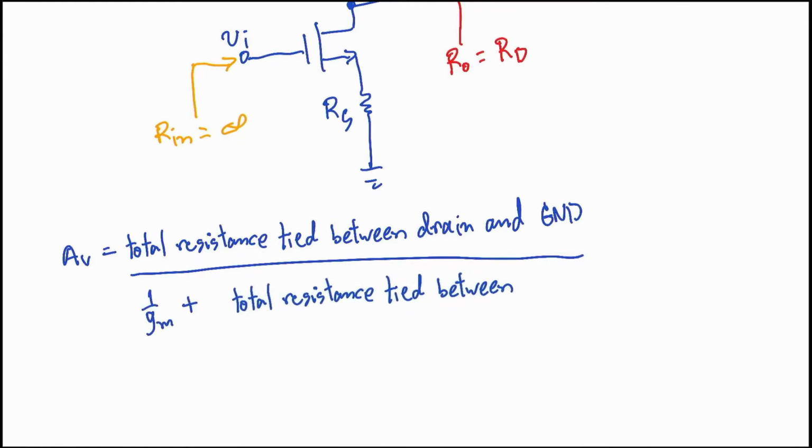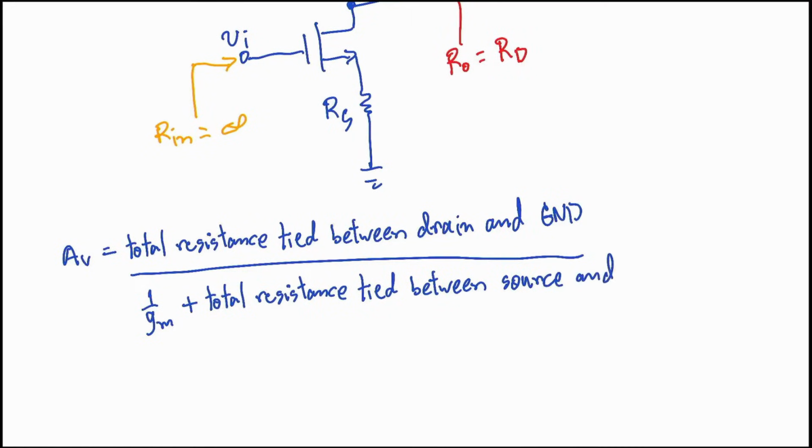When you look at this specific configuration, you can clearly see that the resulting gain, especially when we consider the placement of the resistor R, is actually quite similar to the gain characteristics you would typically observe in a standard BJT circuit configuration. It is a very useful parallel to keep in mind when analyzing these types of amplifier stages. The drain can be compared to the collector pin and the source can be compared to the emitter pin, right? And 1 over Gm is also close in value to Re. Do you see the similarities now? I hope this helps you remember it better.